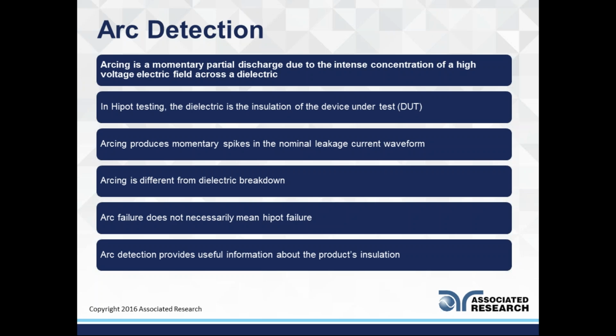With dielectric breakdown, we're getting into a large rise of current, where you're leaking a certain amount of current, and now I'm seeing a gradual but large increase in the amount of leakage flowing through your insulation, where now I've established there's a hole in your insulation, some sort of path from line to ground, or line neutral to ground, between your insulation, where now I can call it a breakdown. A breakdown has occurred, and if I'm applying this much high voltage, too much current will be flowing through your insulation, which creates a dangerous situation.